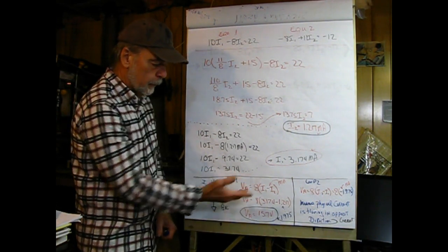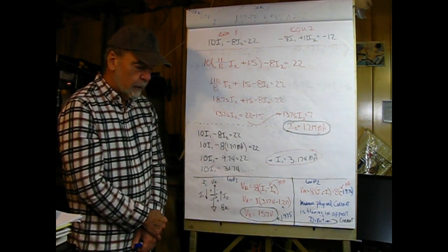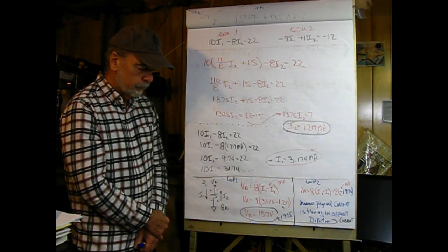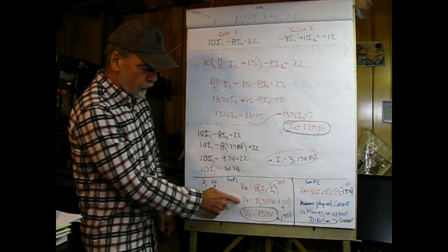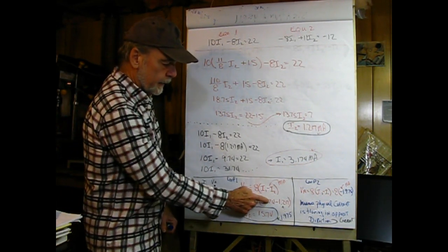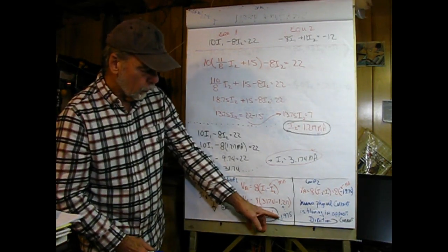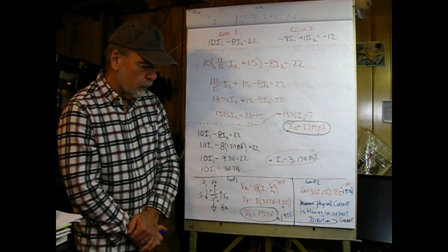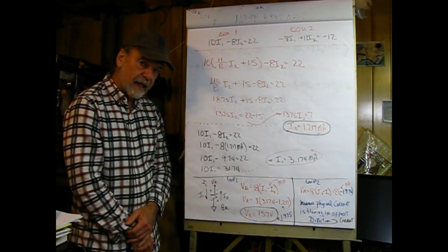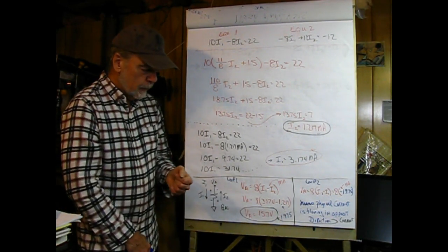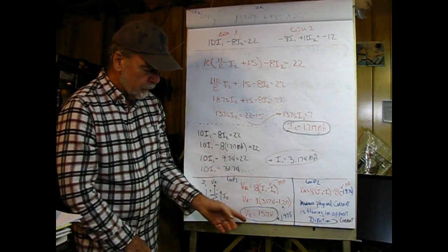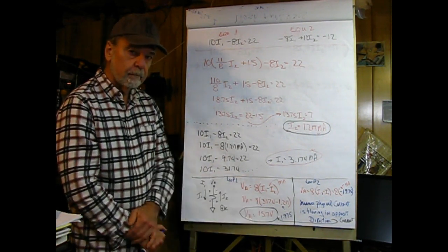This would be in milliamperes and kiloohms as before, and that simply comes out of equation number 1. Then I substituted in the values that I got. These are the mesh currents, and the total mesh currents when you do the subtraction is 1.975 positive, and then solving for VA I get 15.7 volts.